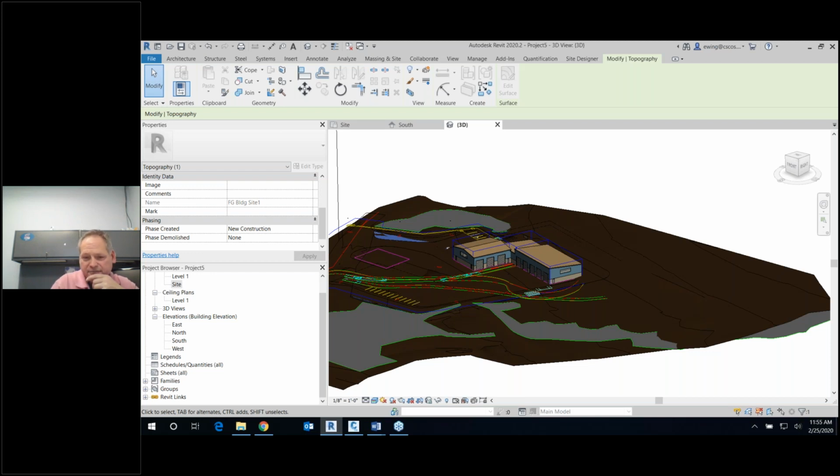If you're not doing that kind of measurement or that kind of layout, you don't have to move the stuff around, right? And I think that's why they removed the paperclip icon from the project base point. It used to be that when you moved it with that clip, you physically relocated the project. You're not doing that now. It's just moving it based on the northing and easting on the state plane coordinates. So again, there are multiple ways to do it. I'm more comfortable having those in known locations.